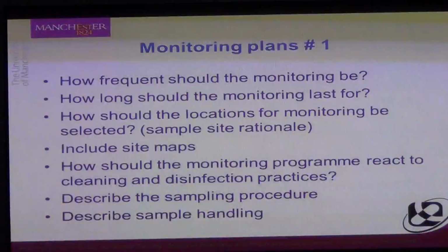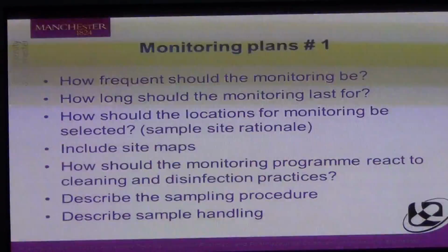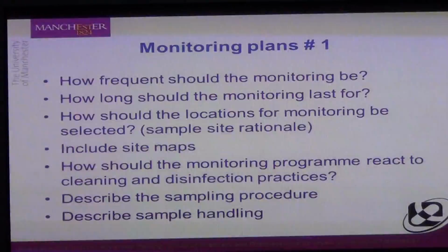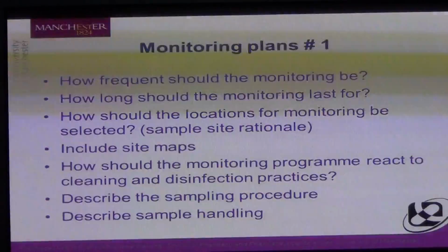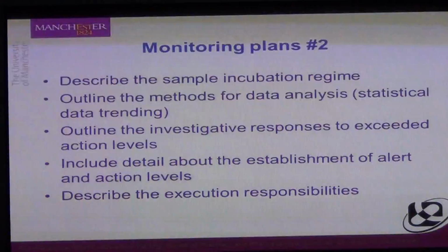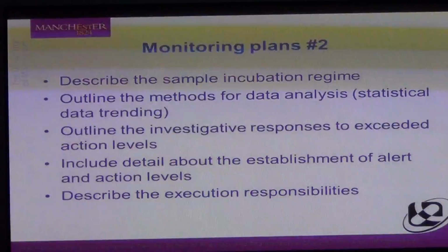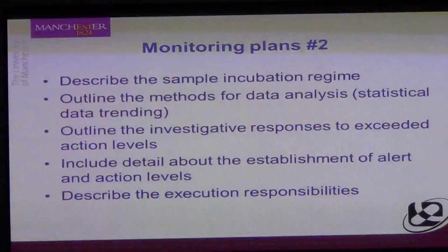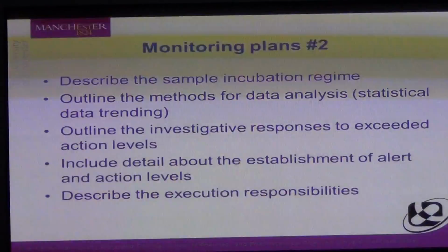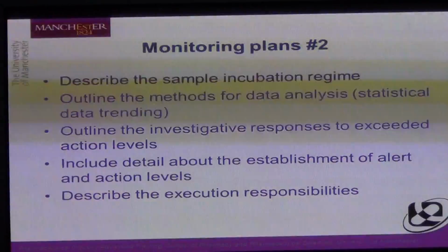Should your monitoring plan reflect cleaning and disinfection practices? Do you go monitoring straight after cleaning or just before? Or would you go at any time of the day? You need to describe the sampling procedure and sample handling. You also need to describe the sample incubation regime, outline the methods for data analysis, outline the investigative responses when you exceed action levels, include detail about the establishment of alert and action levels, and describe who will do the sampling.